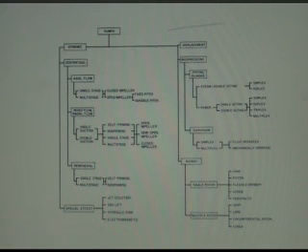This is a chart that shows kind of how they're broken down. There's also a group that's called the special effect, which are the eductors and lift gas style, which inject gas into a fluid stream and bubble the fluid to the top, acts as a pump, but there's no moving parts. You might notice that there's a lot of similarity between this and the compressors that we were looking at the last class. And that's actually not an unreasonable expectation. You have some of the same problems, how to increase the pressure of a fluid. You have some of the same physical properties, and so it's not unreasonable to expect that the results may look fairly similar as well.